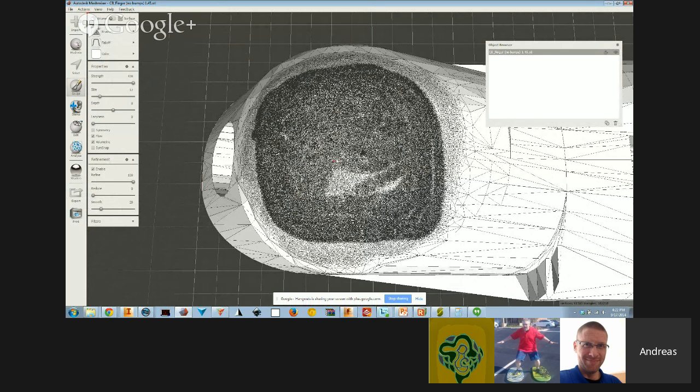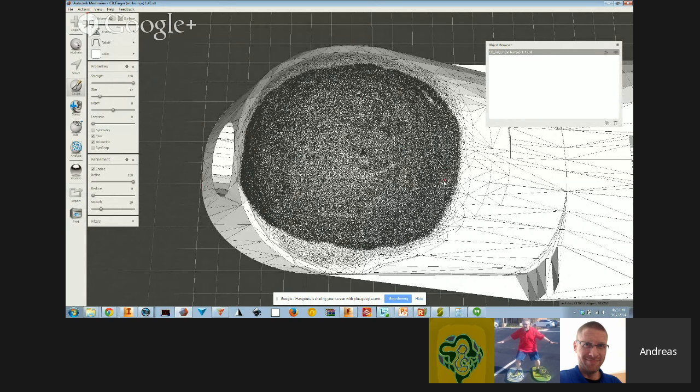Well, in certain cases, the support material goes away sometimes while you're editing the object. So if you are in the 3D print screen of Meshmixer, and you create the support structure, but then you move the object, it'll remove the support structure since the object's been moved in relation to the print plate, in which case it would need to be recalculated. So there's one case where it may have disappeared.